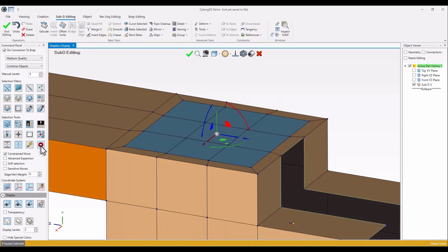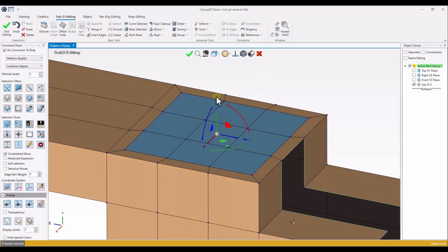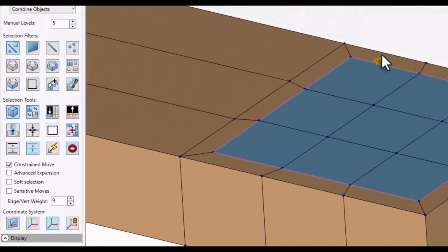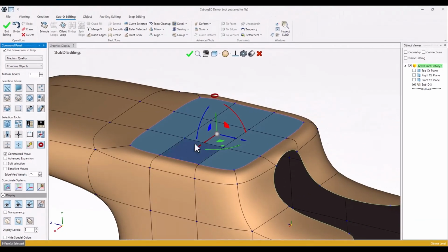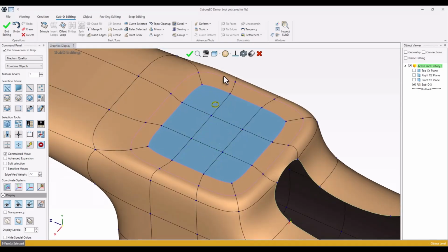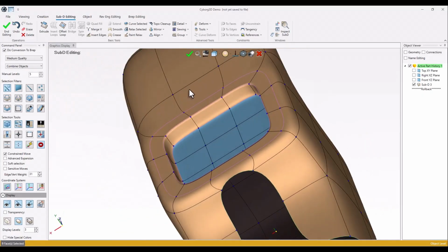I have this little guy here for creasing. So I'm gonna click on it, and you're gonna notice it's just giving me a circle on the top of the gizmo. You can see here it's changing the parameter of the creasing while I'm just moving up and down. And if you go to the sub-D mode, you can see I'm just changing how much crease I'm adding. So let's say this one gonna be 80, and I'm gonna hold the A key again and bevel inside and crease again, extrude and crease. So it's just that simple.